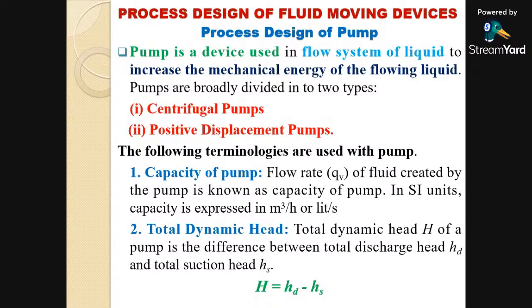So it is possible that a 0.5 HP pump may deliver water up to a certain height. It has some capacity, it can deliver water only up to 5 meters or 10 meters of height. So you need to specify your own requirement to the vendor so that he can suggest a suitable pump. Is it clear? Because until and unless you tell them about your use or requirement, they will not be able to provide you a pump of the desired capacity.